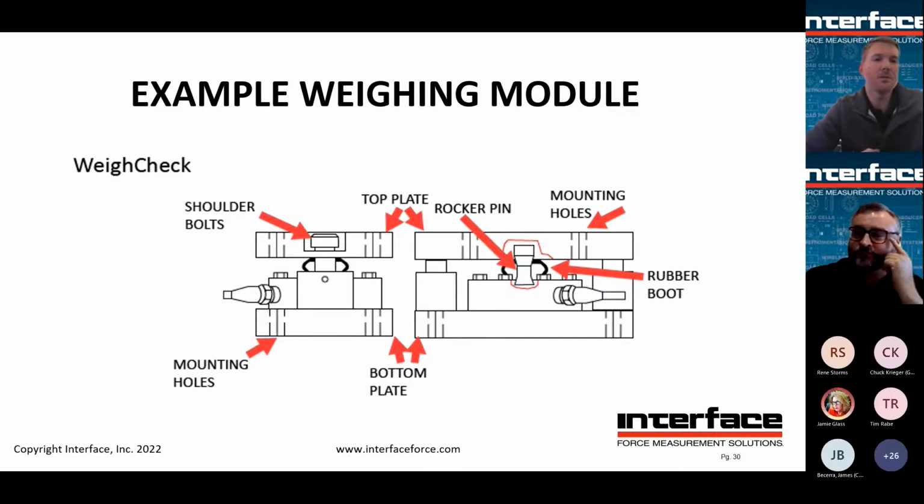Yeah, and one other thing is, all of these need to be on the same plane. And if you don't have a perfect floor or all your legs aren't all the same height, typically these come with a shim kit as well to make sure that we're all going to be flat and level.